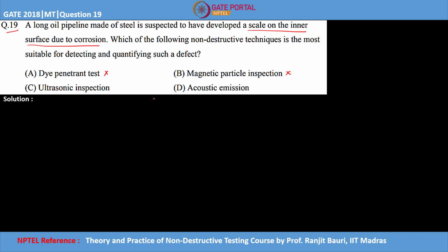We can even calculate the thickness of the material, because when we send a sound wave, it will be reflected back from the back wall, that is the internal wall of, let's say, the pipeline. So it will give a back wall signal as well as the front wall signal. From that we can calculate the thickness of the material.